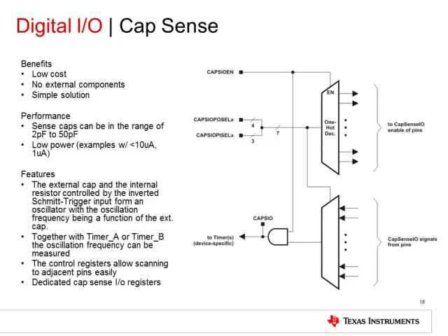Any GPIO can be switched to capacitive touch state by enabling a bit in the control register. The resultant oscillating signal from the Capacitive Touch IO is measured via an internally connected timer. Analyzing the timer values allows the end application to determine if a touch has occurred. The Capacitive Touch IO module allows the application to be low power with its autonomous operation and also results in lowered system cost due to reduced external components.